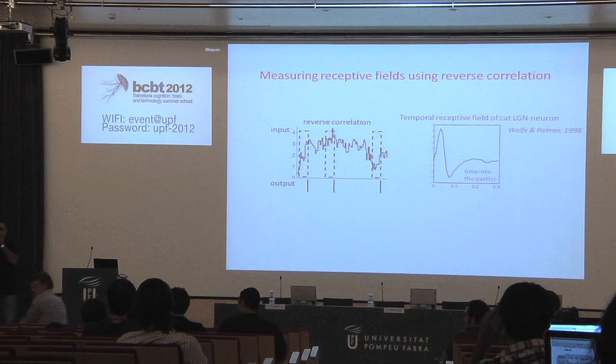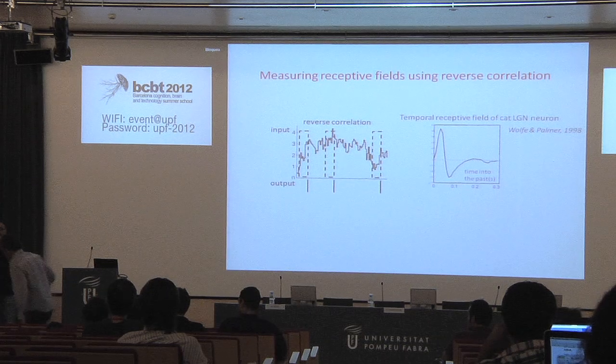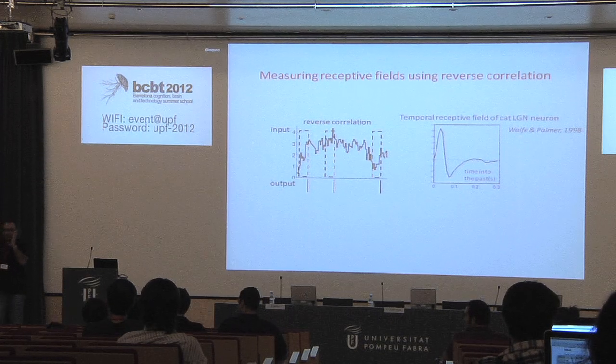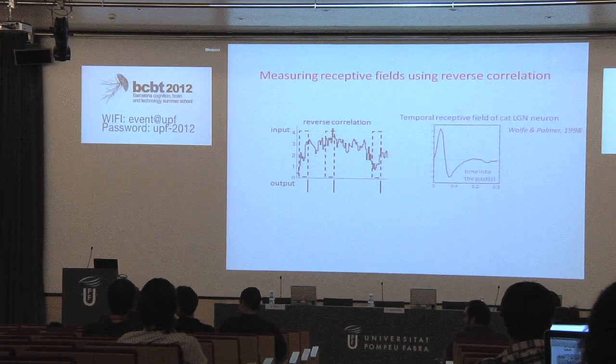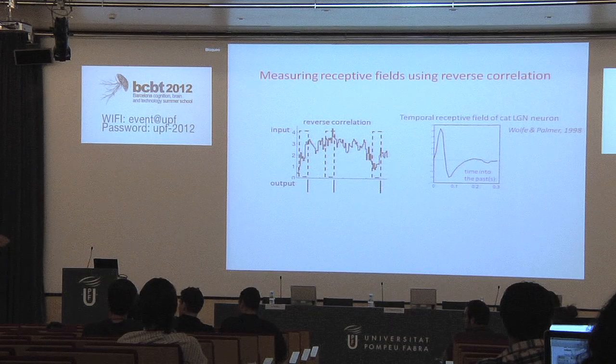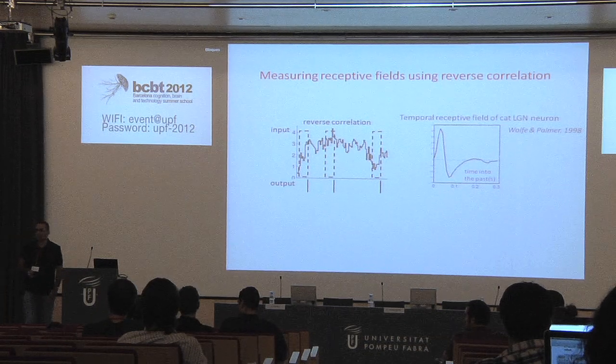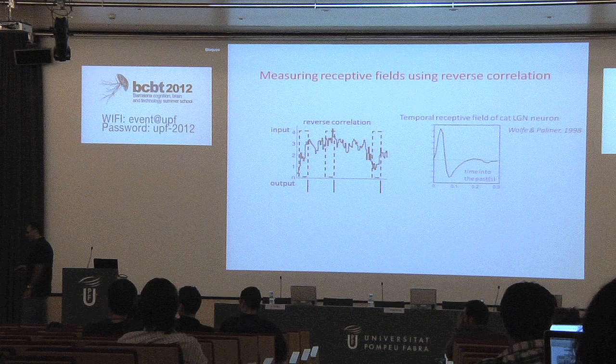Is this related to what are called matched filters in detection theory, where you're trying to see signal and noise? I don't know what that is. I think it's slightly different. Sorry if I may comment. Yeah, please. It's a related concept, but I think it's slightly different. In the matched filter, you're looking at the spectrum of the object you're trying to detect, and you're trying to tailor the filtering of your system to match the spectrum of that object. So your system produces a maximum signal for that object compared to everything else that's around.